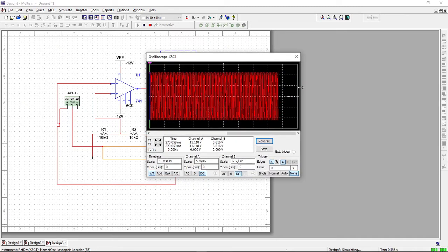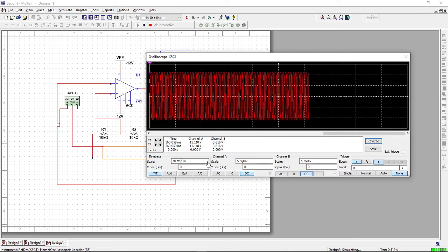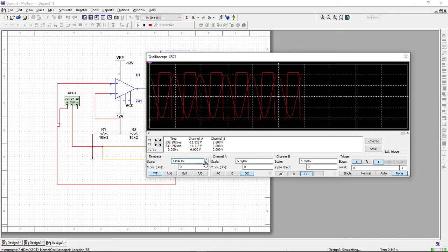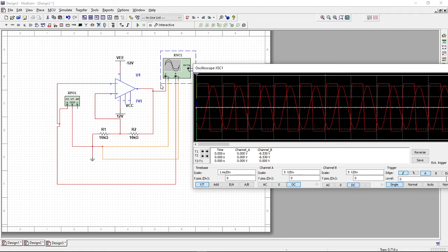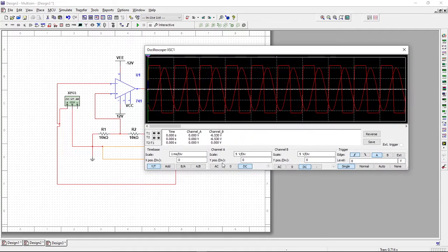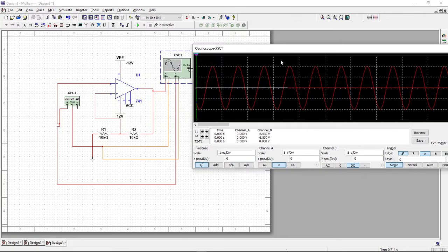Yeah, the waveform is so bulky, so I am increasing the time scale so I can see both the sine waveform and the square waveform. It might be a little confusing, so I am grounding. Here 0 resembles ground. If channel A becomes grounded, then the output at the 6th pin will be grounded. That means there will be no resulting output waveform.